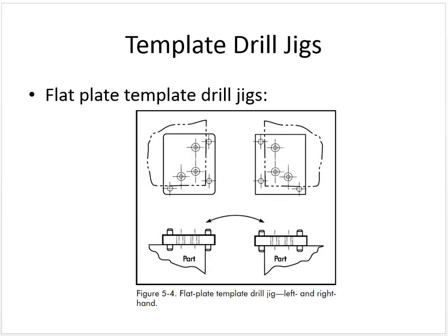Here are some other template drill jigs. This one has some locating pins. You place it over the top of a big part, and then you have these 3 bushings for performing some operations, just like we're showing here. That's a template drill jig.